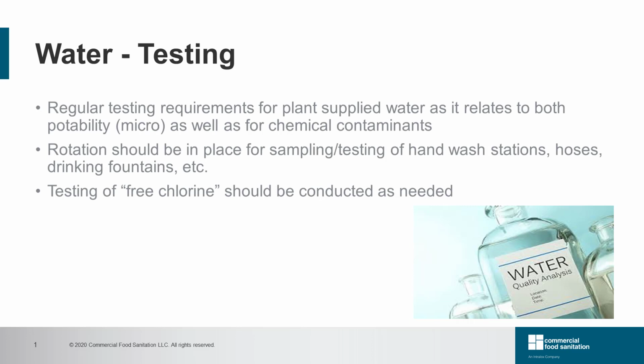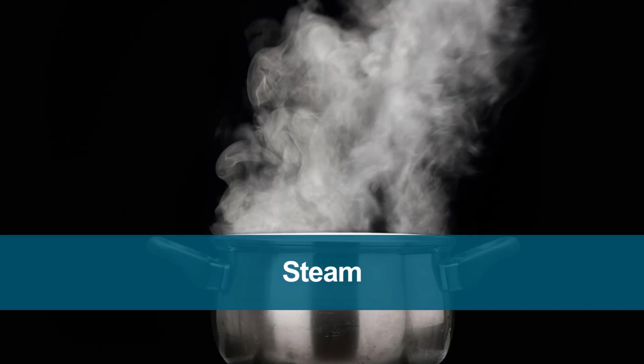Water should be routinely tested to ensure it meets micro requirements as well as chemical requirements. Testing of free chlorine should be conducted as needed. Sampling and testing points should be rotated within the plant and should include hand wash stations, hoses, and drinking fountains.